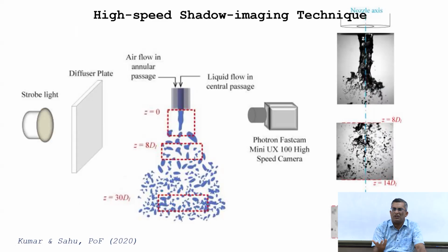So, if you are having a particle of say size 40 micron, and your resolution is say 10 micron, that is each pixel is 10 micron, you need at least 3-4 pixels to identify one particle. So, in that case the sizing accuracy will go down.